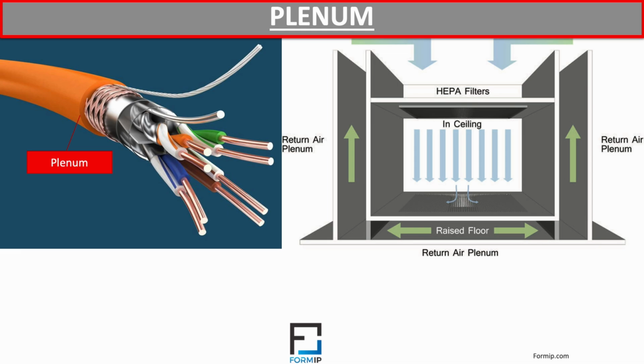The term plenum refers to a space in a building where there is free air circulation, and this is generally located between the suspended ceiling and the structural ceiling. Plenumless buildings have ducts that encapsulate the airflow. Plenum buildings, on the other hand, have an airflow that circulates in the false ceiling and are therefore more prone to fire than non-plenum buildings.